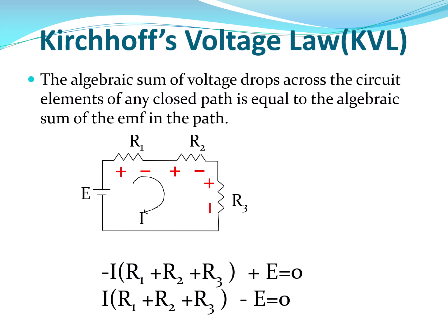So at this point, the potential will be less than E, isn't it? As the potential is dropping across a resistance, before that resistance the potential is more, and after that it's less. That's why it is denoted as plus minus. Similarly, in the case of R2 and R3, we have denoted plus minus. So at the end of R3, the potential will be 0. The total voltage will be distributed among R1, R2, R3. Some part is dropping here, then another part, and the rest is dropping here, and here the net voltage is 0.